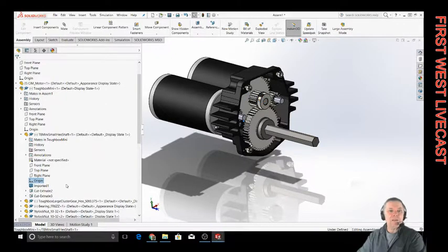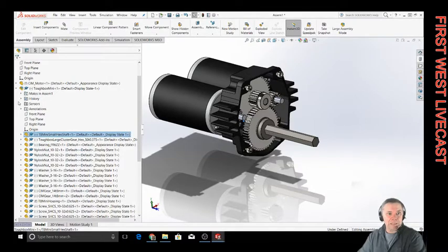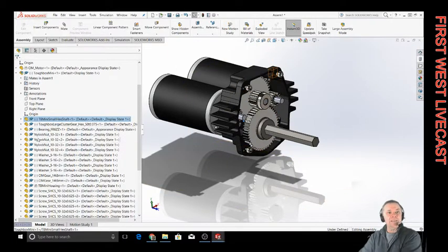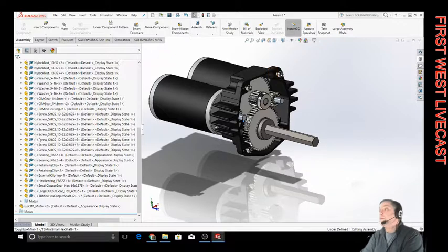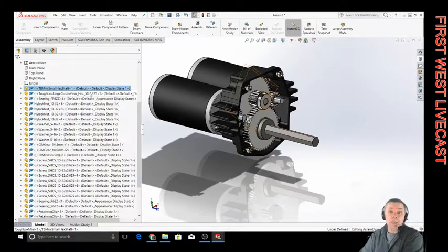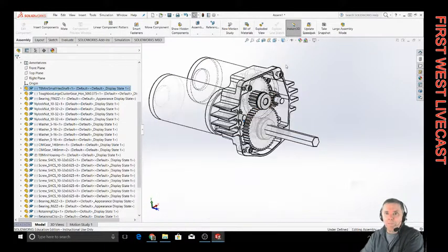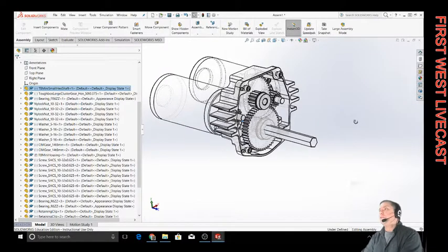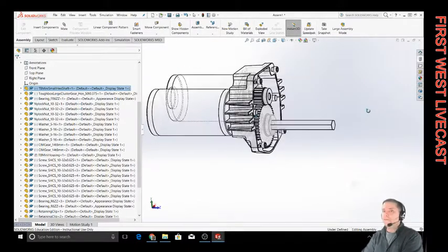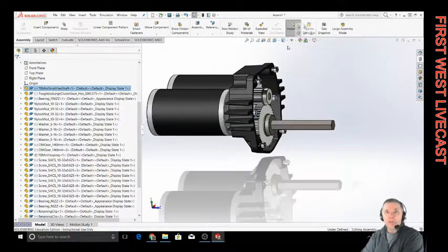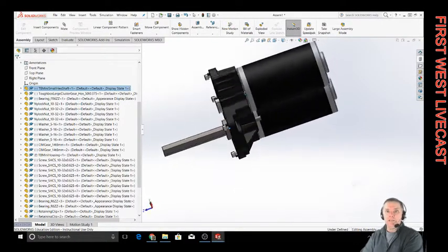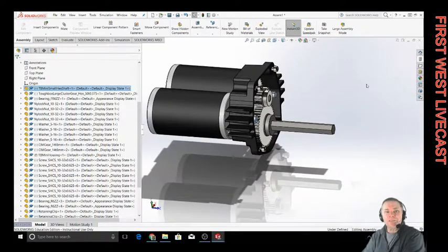All right. And this parametric table on the side, this features table, gets to be pretty large after a while. Now, if you find that your system starts to bog down, like mine did, as I said, you can actually switch over to Wireframe, like this, and that takes a lot less processing. Work moves a lot faster, and then bring it into a solid model when you're actually ready to look at it in all of its awe and beauty.